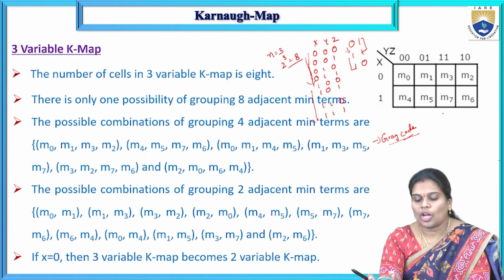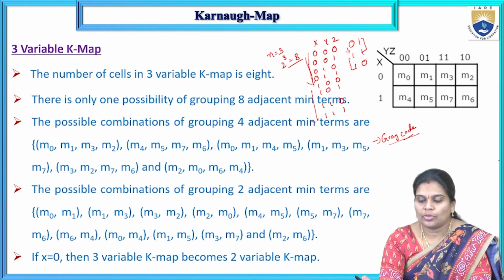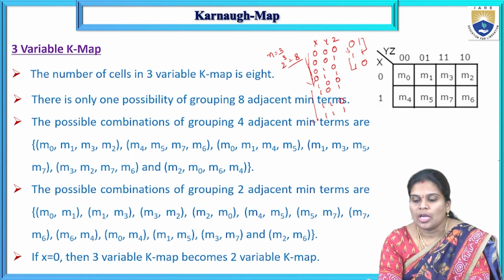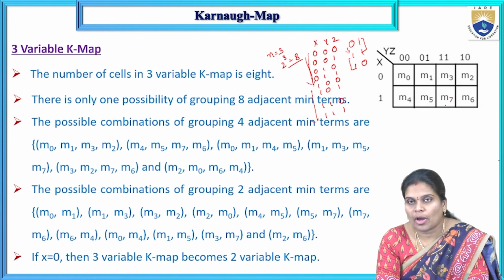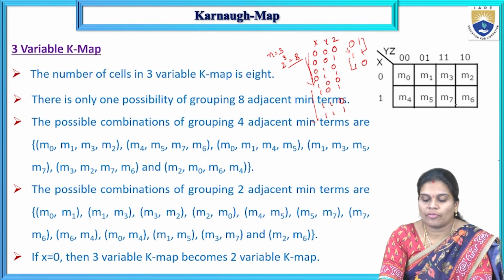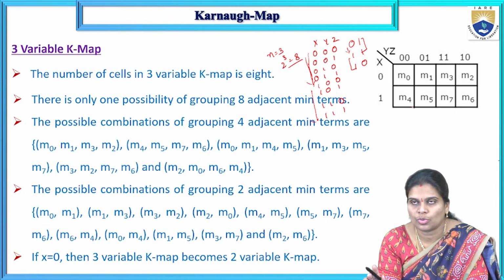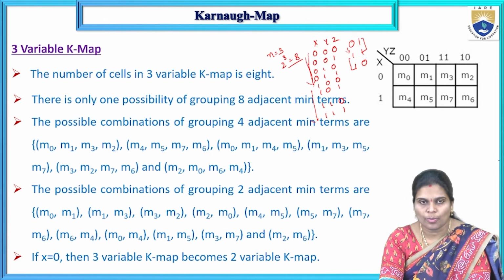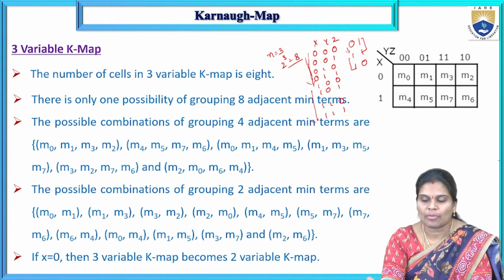Okay. So now this is the three variable K-map. Now we are taking any Boolean expression. How are we forming the groups? First we are observing the ones. Generally, in any K-map, we first take the maximum number of possible ones to form one group. Next, the next maximum number of ones forms the next group.